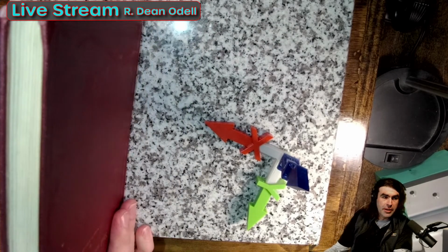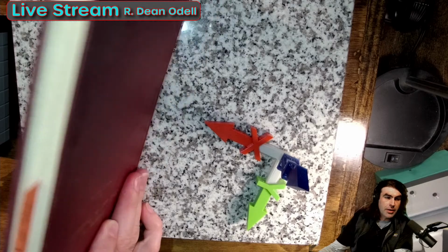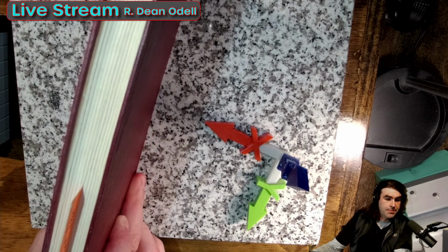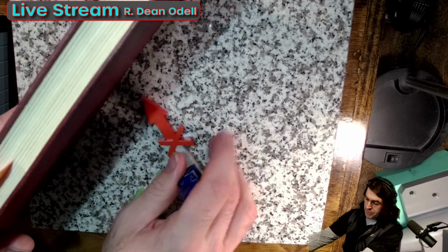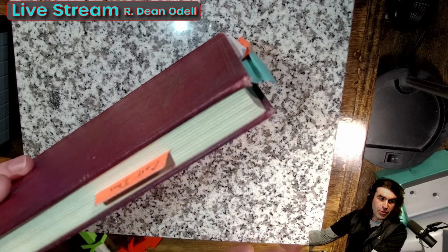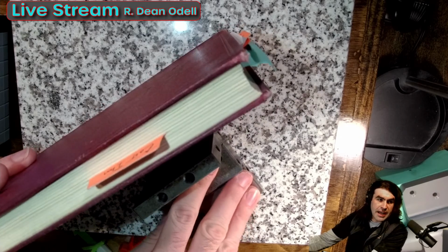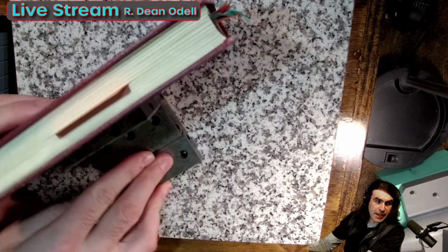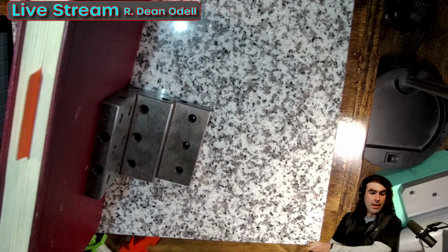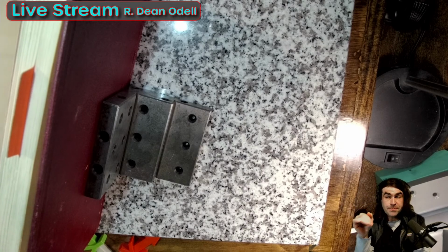And we're going to say this book here is datum B, right? The book just needs to be 90 degrees to datum A, right? It's 90 degrees, but it can still rotate, even if it's directly 90 degrees to the plate. You can kind of imagine that as being propped up by this block, but it's still allowed to spin, right? So that's why we can use perpendicularity with the secondary datum.